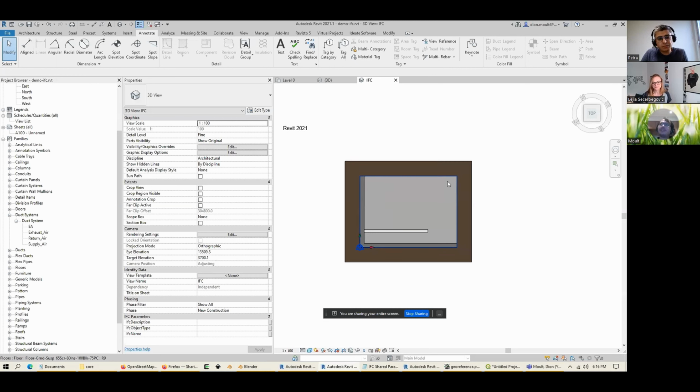Correct. So there's really two issues here. One is tolerance, which until you're really hitting that 20 mil mark when you've got a 300 meter long site, that's when you start encroaching on the concrete thing. And it also depends if you're doing a modular, with steel, modular across a long site. That's another issue with buildings. Smart likes to give it as an example where this becomes a real problem. Otherwise, you're right, it does get absorbed.